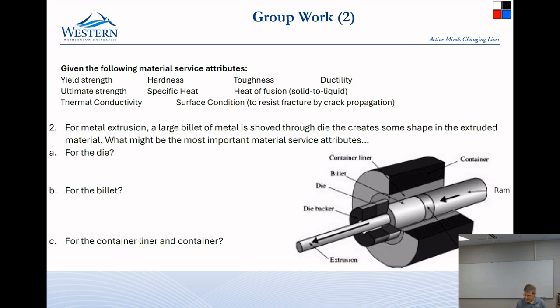Ductility, or rather lack of ductility. You'd like to have ductility, yeah. So you'd like to be able to reform the shape of this as much as possible. And so we measure the ductility. We talk about reduction in percent area. This is way outside what we could normally do. Some of that is because we have it in compression all around, and so it keeps it from cracking, and some is because we heat it. But this is a huge amount of ductility.